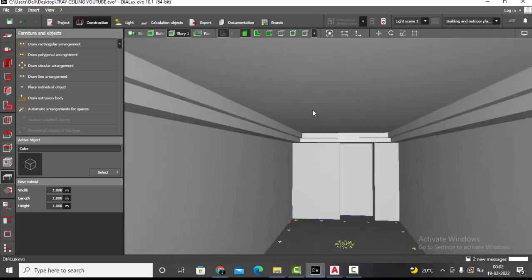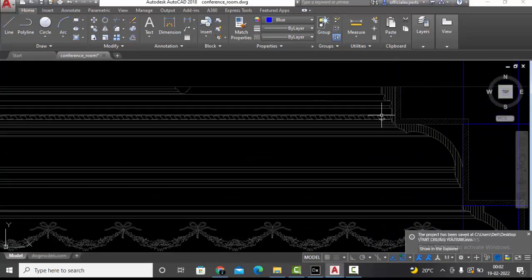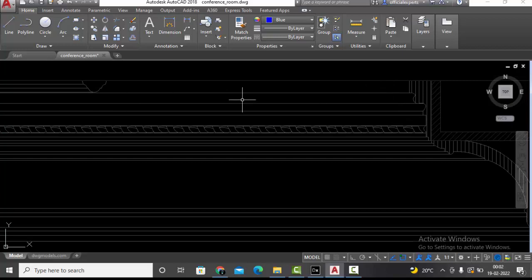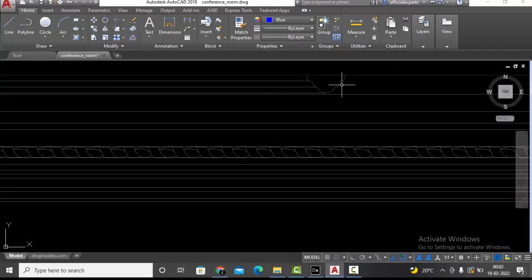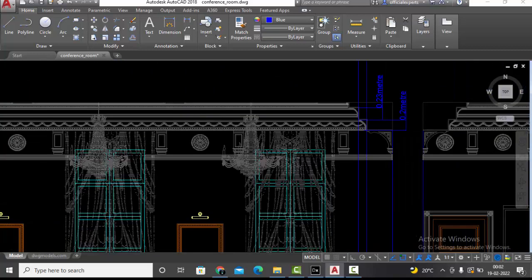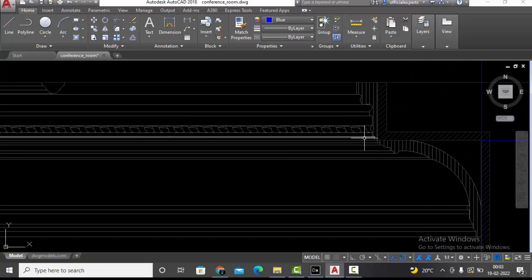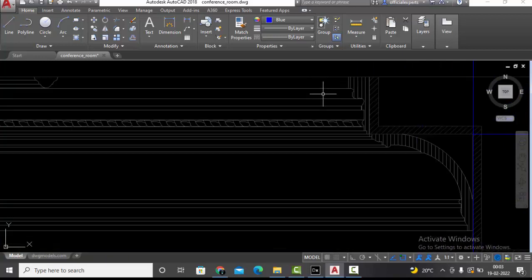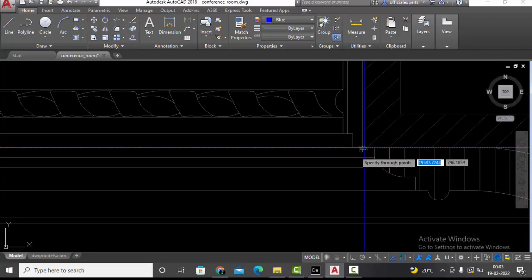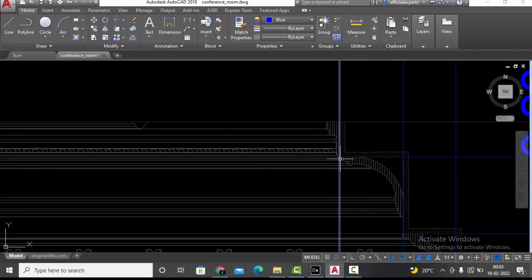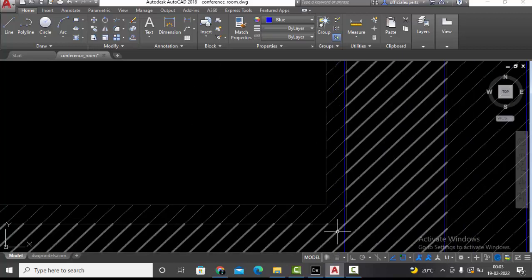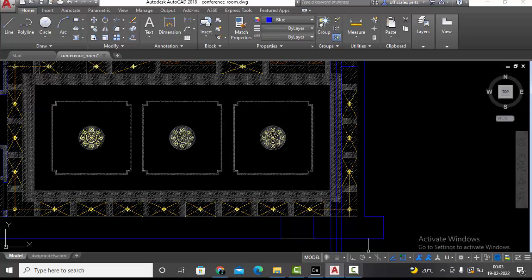You can see how nicely the ceiling is coming out now. Next we are left with our third cutout, which is this one. See this clearly, it is ending till here, but we have one more detail, which is of this one over the top over here. So it means my next cutout should be till the top. Okay, and which rectangle do I have to consider? Let's check XLV, and from here the next ceiling level starts. So I will draw the X reference line here, and it is the second innermost rectangle I have to consider to draw the cutout.